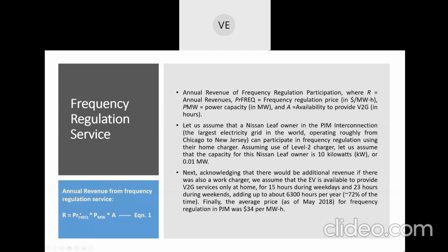So the charge or the price for frequency regulation is given like this. It is charged for the capacity, which is communicated prior to the frequency regulation time horizon. Suppose I'm going to participate in frequency regulation service. If it is an hourly horizon, suppose from 3 p.m. to 4 p.m., then 1 day before or 1 month before itself, I'll commit. I'll say that for these many hours, I'll be committing my electric vehicles during this time period at this capacity. That is this capacity, 10 kilowatts.